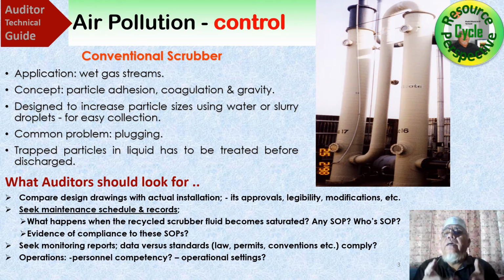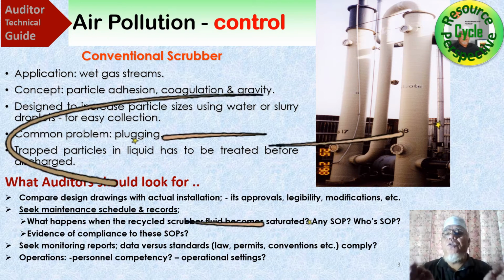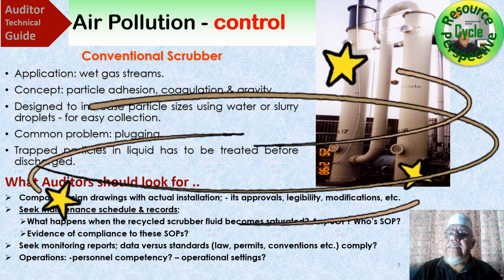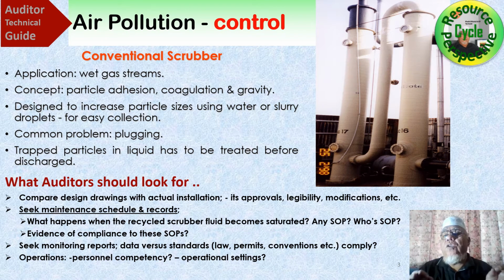Being denser, the newly formed droplets shall obey the law of gravity and sink to the bottom of the chamber as scrubber liquid. This liquid, however, is being reused as scrubbing agent over and over again until it gets saturated. Then this contaminated and dense scrubber liquid must be released and replaced by fresh scrubbing agent.